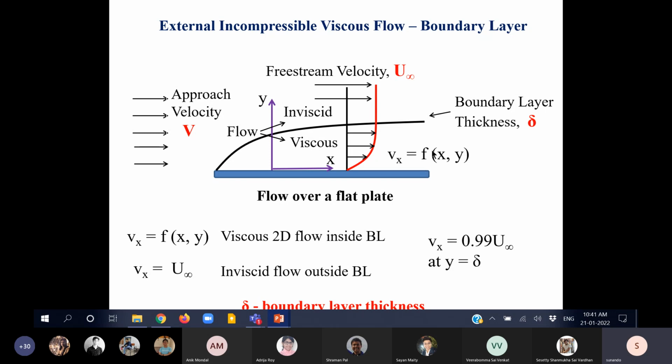So if you have low pressure at this point and high pressure over here, because of the formation of the wakes, formation of the boundary layer, and the detachment of the boundary layers from the surface, which causes the wakes, this produces a force which is the force required to move it towards the left with a certain velocity.